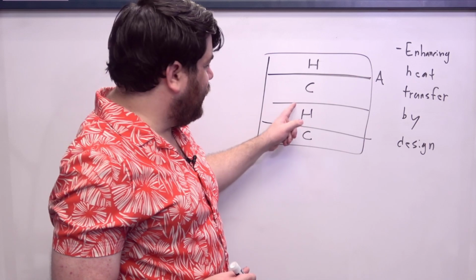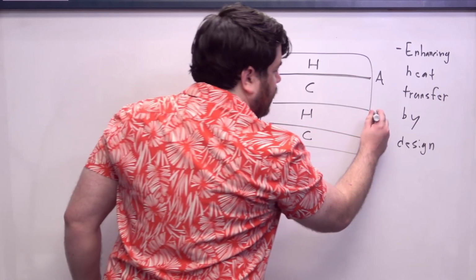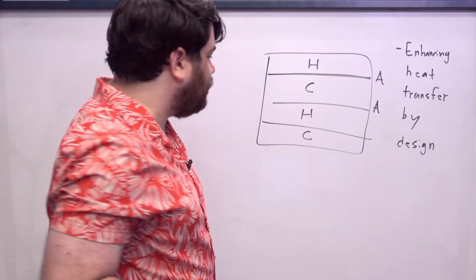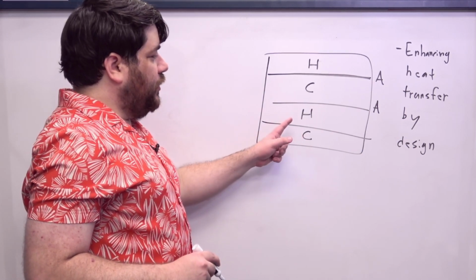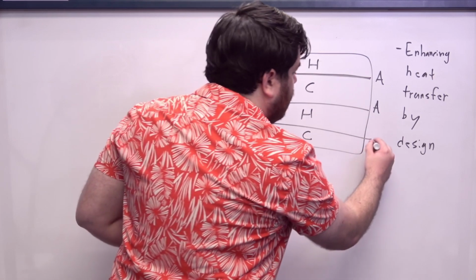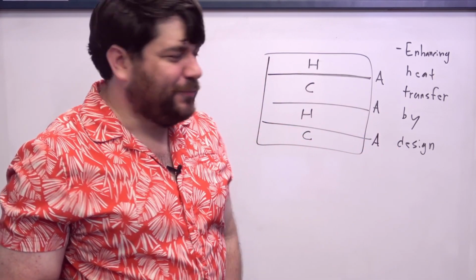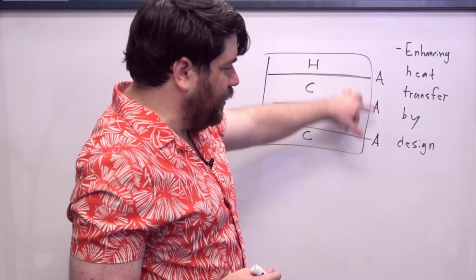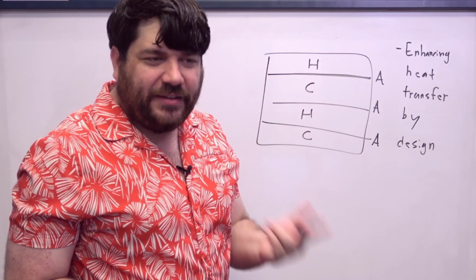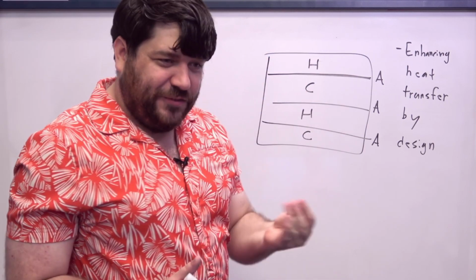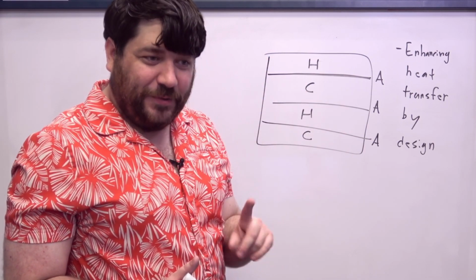So heat transfer is going to occur through this surface area too, which contributes another A, another effective A. And then we observe that the same thing is going to happen right here. And so if you calculate out what this looks like, we've tripled the effective surface area over which the heat transfer takes place without changing the external geometry of the object, okay?